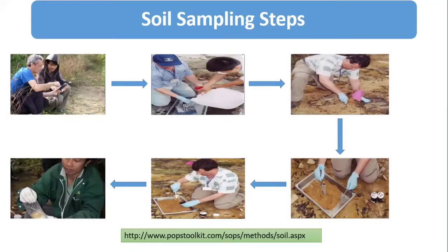Then once we reach the laboratory, we can see that there is fading of your marker, which means the mark. Then you will get confused: which sample did I collect? Is this A2 or B2, something like that? To avoid this type of confusion, you have to cover your labeling with proper sellotape. That means you have to make sure that this is waterproof.